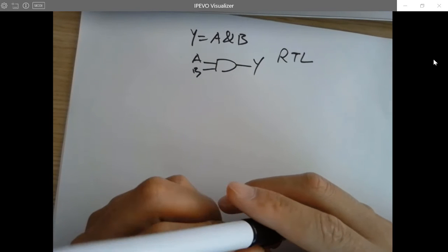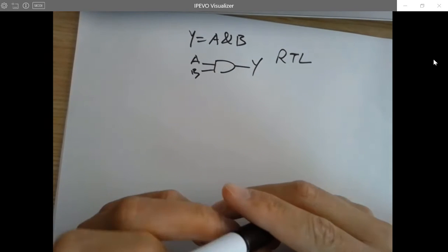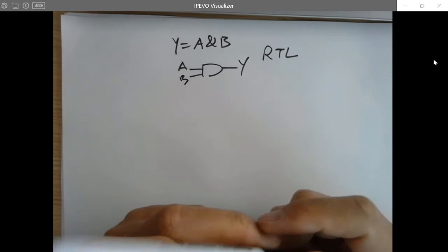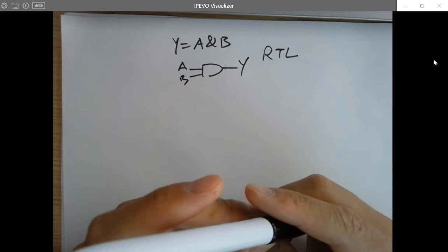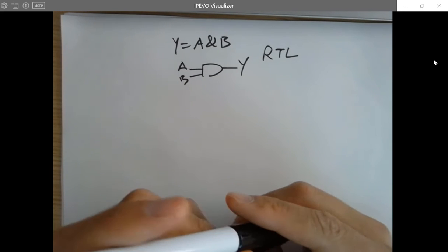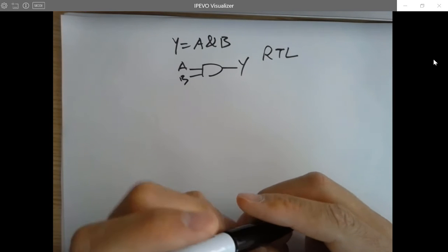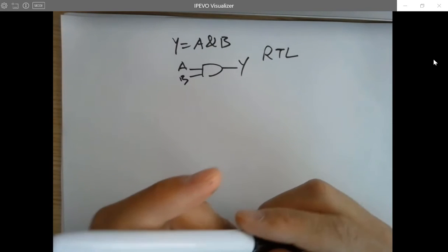And the program will be read into DRAM in the chip. DRAM doesn't require high voltage. And it's volatile, which doesn't matter because flash is non-volatile. So the flash off the chip can memorize everything. But DRAM will just temporarily receive everything through SPI from the flash and send it to the CPU to do the calculation.